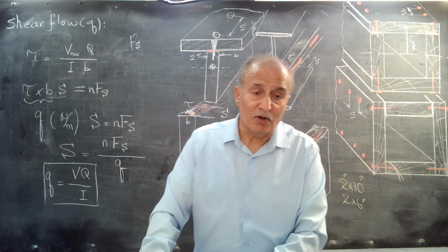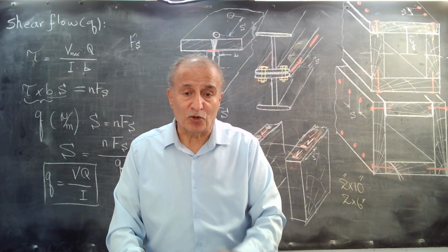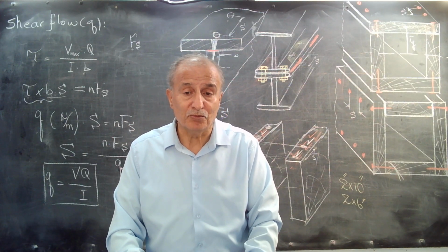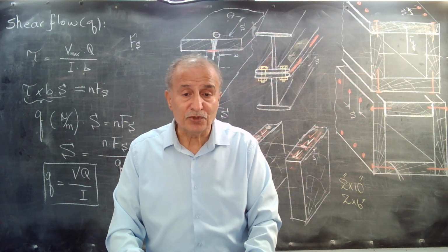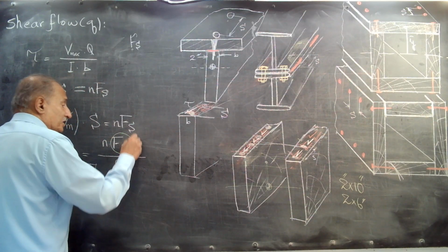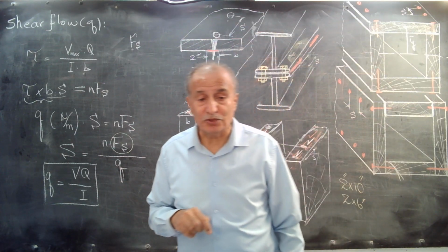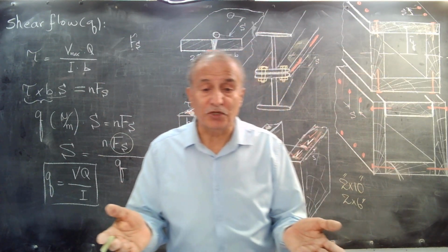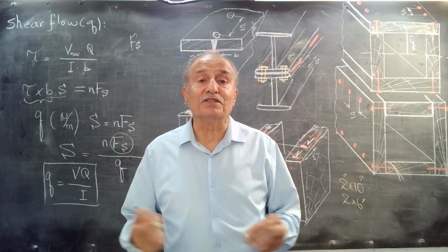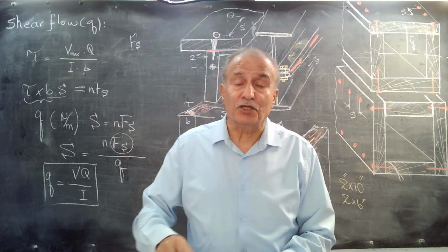Then, you know what shear flow is and what its application is. And you can solve many problems for built-up beams and find the spacing between nails. But they must give you the characteristic of the nails. The shear strength of nails or bolts or screws must be given. When you are buying from the market, you must know how much the shear strength of this nail or fastener is. Thank you and bye.